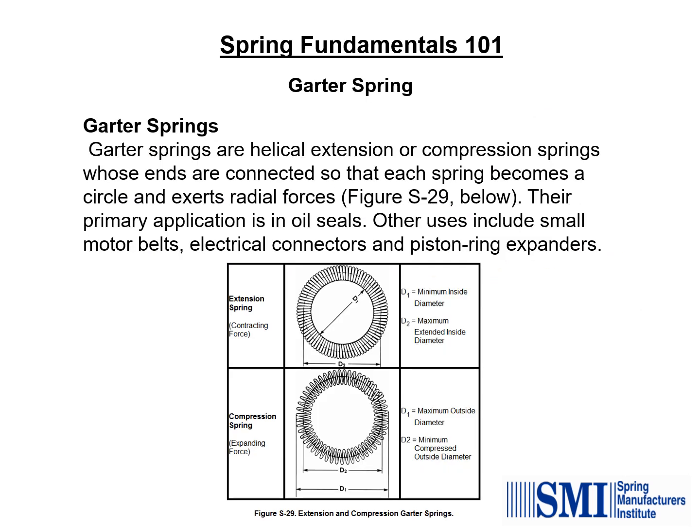Garter springs are helical extension or compression springs whose ends are connected so that each spring becomes a circle and exerts a radial force. Their primary application is in oil seals. There are other uses also, including small motor belts, electrical connectors, and piston ring expanders.